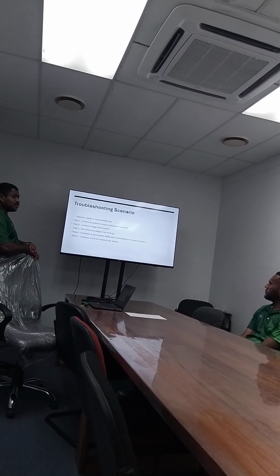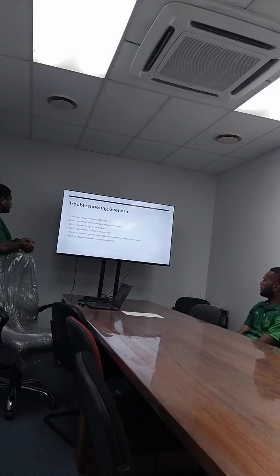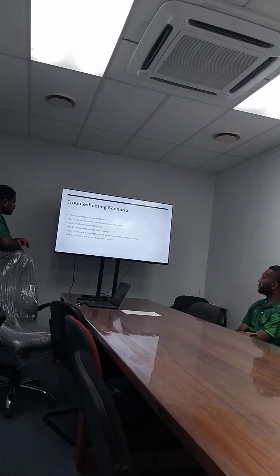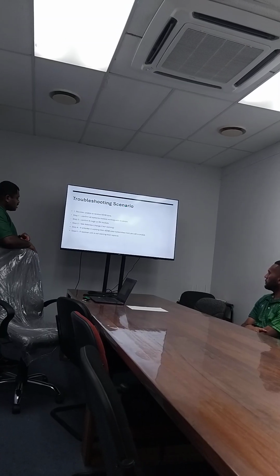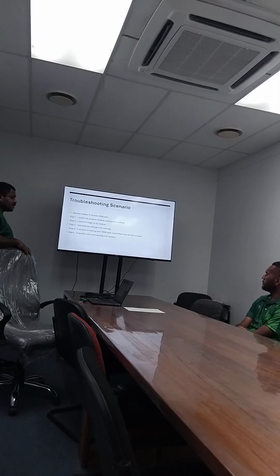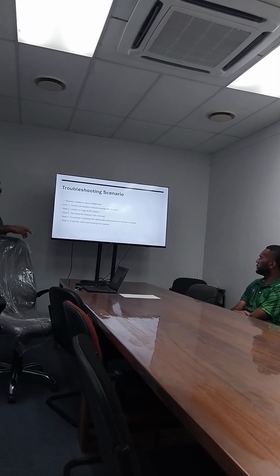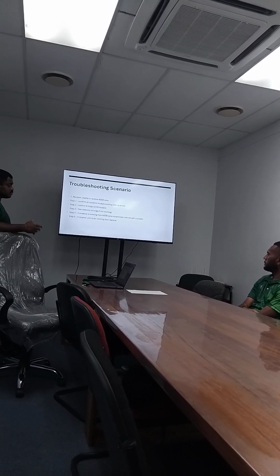We went on one fault on Thursday. The station was not booting up. It was basically a control line for a remote control, and it was inhibiting the modules from powering up. So we had to go and do fault solutions. Then we observed and uncovered that there was a relay that was burned.